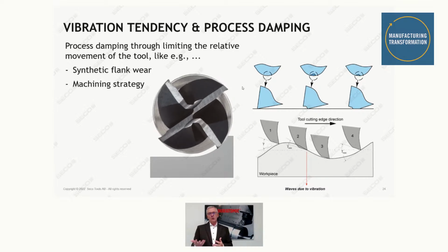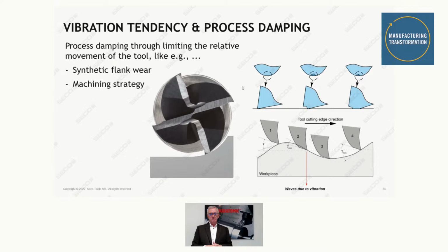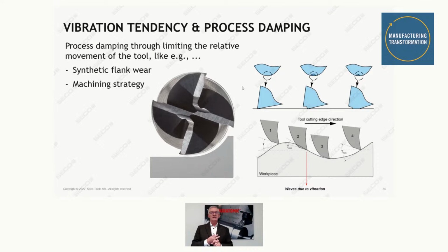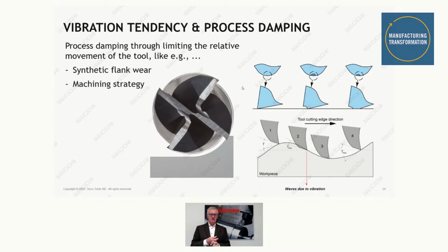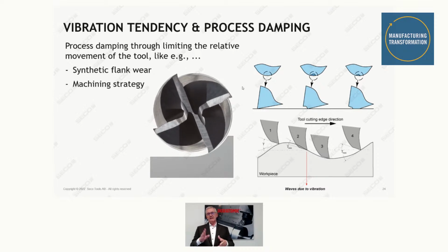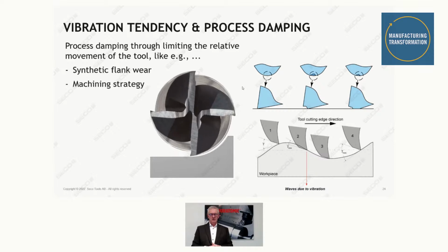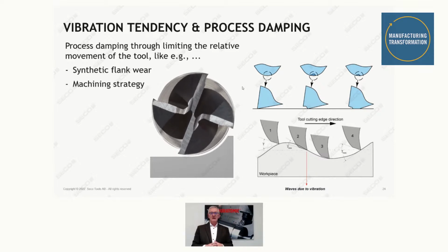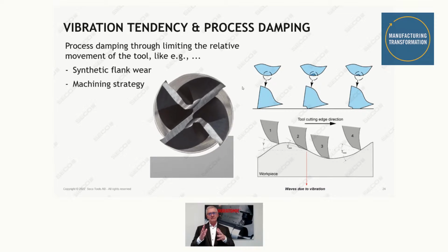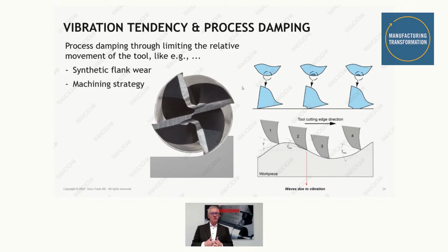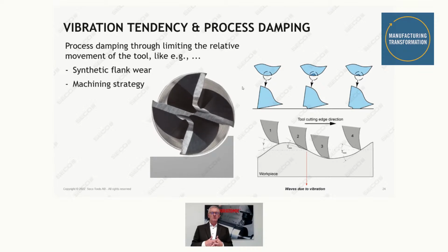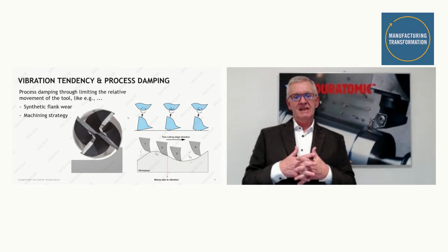You can also force a cutting tool into a damped position by selection of cutting conditions or by the selection of the machining strategy. I suppose you all heard about dynamic machining, and lots of people tell lots of things. It seems to be the big game changer in machining anyway, but part of the advantage of dynamic machining is that we force a tool into a fixed contact situation between workpiece and cutting tool.